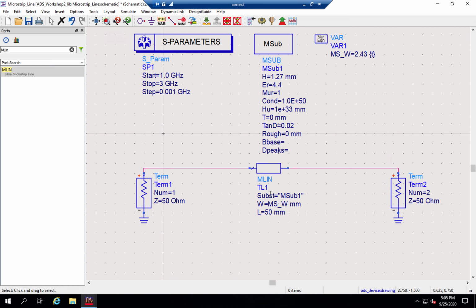Okay, so if you guys are paying attention, you'll notice that compared to HFSS, here I'm defining a certain port impedance. So I'm fixing the impedance of the terminations to be 50 ohms and 50 ohms. In HFSS, if you wanted to do that, you would have had to do not renormalize the waveport and then force the impedance to be 50 ohms.